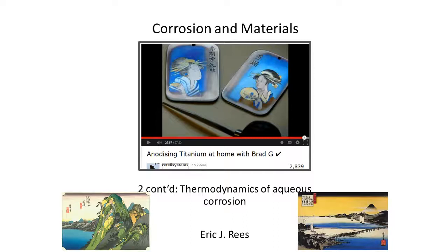If you watch the YouTube clip though, the artist has used a high voltage etching pen to artificially electrochemically corrode the material to make the passive oxide thicker, and the different colours sketched onto the titanium are actually Bragg reflection colours, or thickness colours, in which the thicker the film becomes, the longer the wavelength of the main part of the reflected light. Because the thickness of the oxide gives you a colour, you can see the passive oxide film on these titanium plates. The coloured bits are, in this case, a few hundred nanometers thick, and so that proves to you that the passive layer really is there.